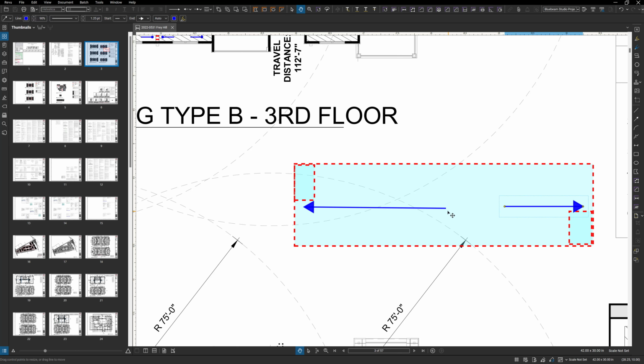I don't have to consider bizarre situations like this where this is 150 feet and this would be 50 feet. Once you get to egress travel distance, you get to count it from the equidistant point between those two egress points, aka stairs, on a given floor. And it is per floor unless it's common travel path.